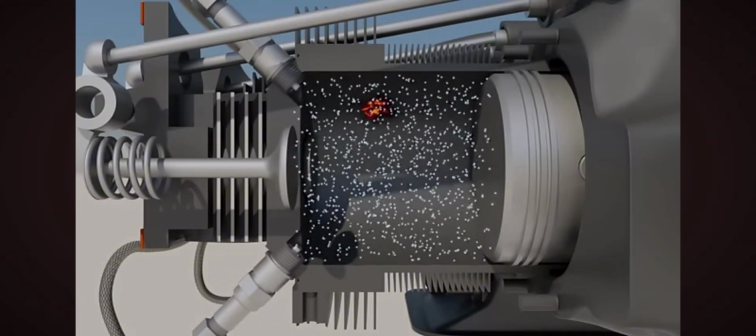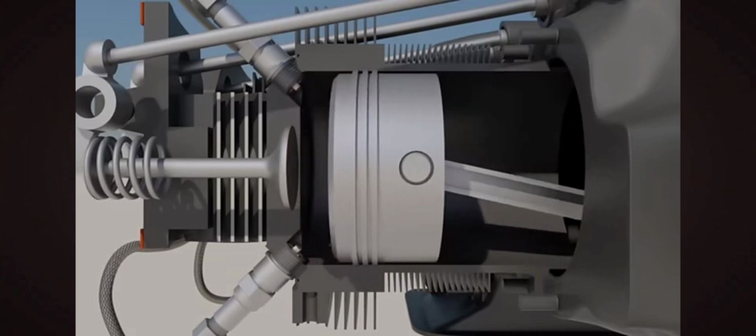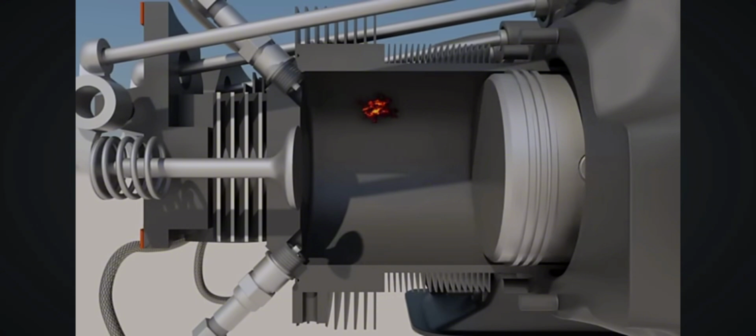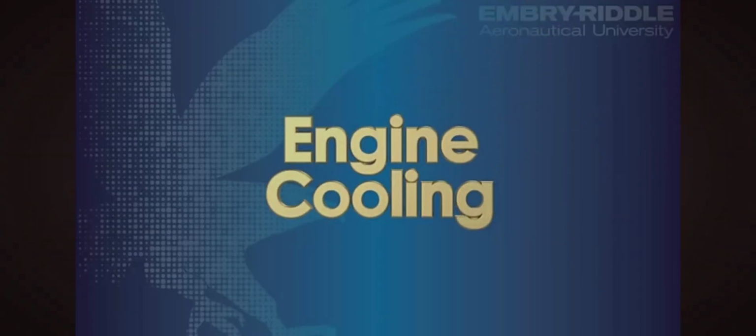Just as you'd expect, pre-ignition is simply when the fuel-air mixture is ignited prior to its normal time. This phenomenon usually occurs because of a lingering hot spot on the cylinder wall, usually caused by a carbon deposit that is hot enough to ignite the fuel-air mixture. Even when the engine is detonating or experiencing pre-ignition, the temperature of an engine can get quite hot.